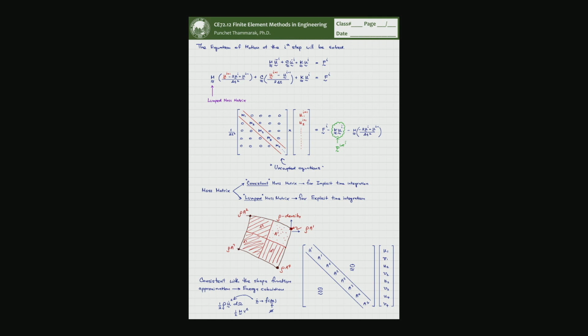Ultimately, what I want is that up to this point, you know all the terminologies about finite element. You know how finite element works. You know from the very scratch part that we developed how the shape functions come up, what is the use of shape functions. The approximation of the displacement is given by the shape functions, right? And we use all of these shape functions and we come up with the stiffness matrix. We discretize the domain into small pieces. We have the degrees of freedom. We try to establish the equation of equilibrium at each degree of freedom.